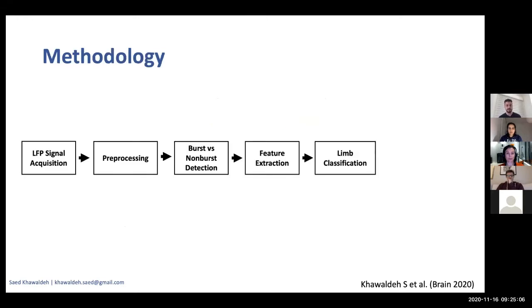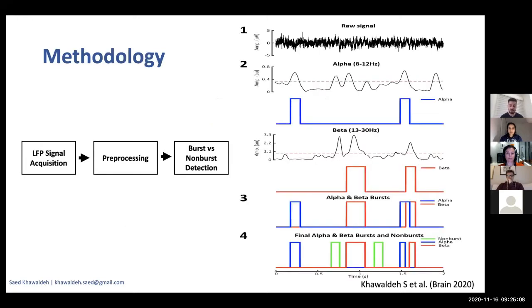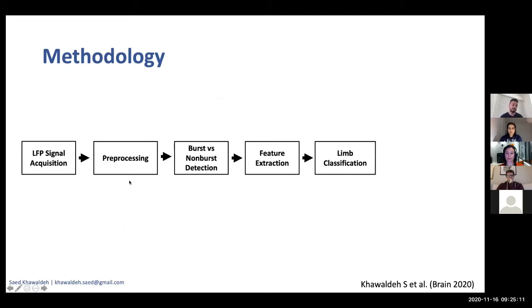Once we had collected the signal, we processed it by doing some filtering. We did a high pass filtering, then we downsampled the signal and did a small artifact removal to ensure that the signal is clean.